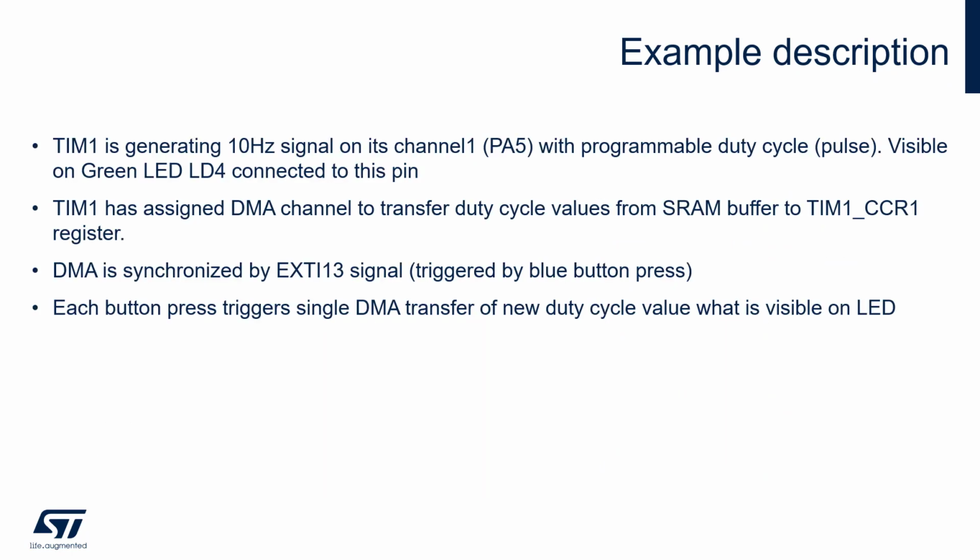A bit more details about the application. Timer 1 will generate a signal of 10 Hz on its channel 1, which is connected to PA5, and with flexible duty cycle. This PA5 is used as well to connect the green LED called LD4. So it's pretty convenient to observe the final effect without any special equipment.